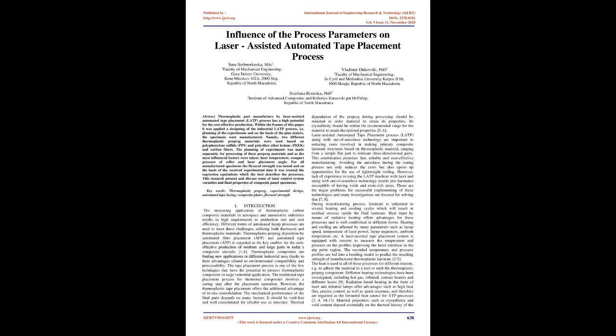The planning of experiments was made separately for processing of these prepreg materials, and as the most influential factors were taken laser temperature, compact pressure of the roller and laser placement angle. For all manufactured specimens the flexural strength was tested, and on the basis of the received experimental data, regression equations were created which best describe the processes.